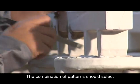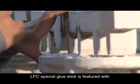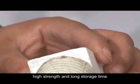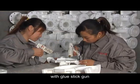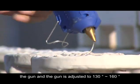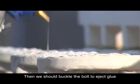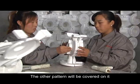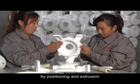The combination of patterns should use LFC special glue stick. LFC special glue stick is featured with convenient use, quick solidification, high strength, and long storage time. The use method: use the glue stick with the glue stick gun. The glue stick is inserted into the back hole of the gun, and the gun is adjusted to 130 to 160 degrees. Then we buckle the bolt to eject glue. The glue is ejected on the pattern, and the other pattern will be covered on it. High strength can be achieved by positioning and extrusion.